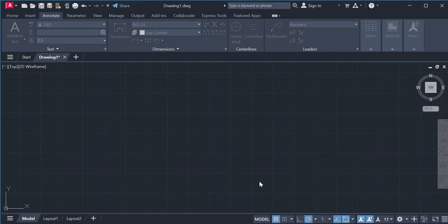Then remember that you're not done. Okay, just because you've done all of that doesn't mean you're done. The next thing you need to do is make sure that you set what you've done as current. So essentially our drawing 2 annotative style, as you set it current, and then you close. So essentially now as you continue with your drawing and you dimension, that will be set.